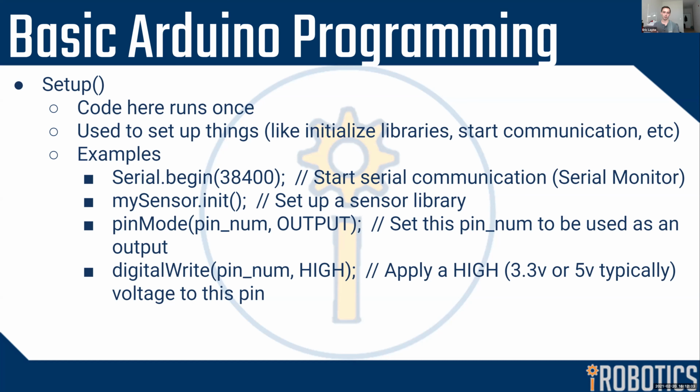But for the input, you don't necessarily need to, but it's generally best practice to say, is this an input or an output for every single pin, just in case for some reason something is weird or you decide, oh, we need to switch to a slightly different microcontroller. It should just transfer over with you changing the pin number and it should be fine. If you assume the default works, it may or may not work if you just copy your code over. So best practice, but not always required.